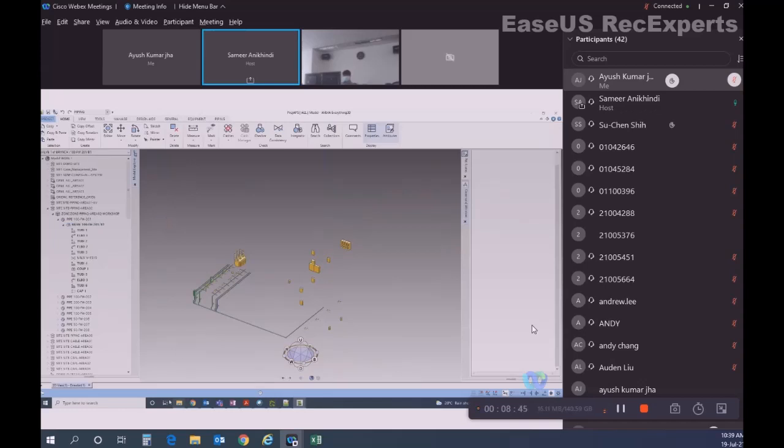You have to save the work at regular intervals, or whenever you finish your work, by pressing save, Control S, or there is another way. Right click with control pressed. Without control, this is a different menu, but with control, this power wheel becomes a different menu. So here is save work and here is get work.